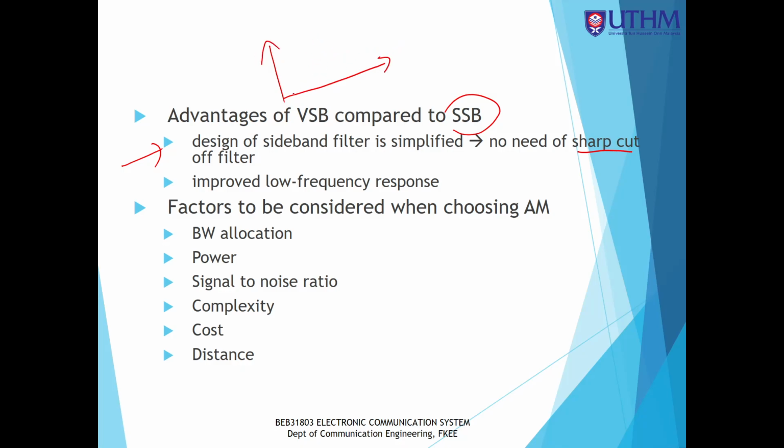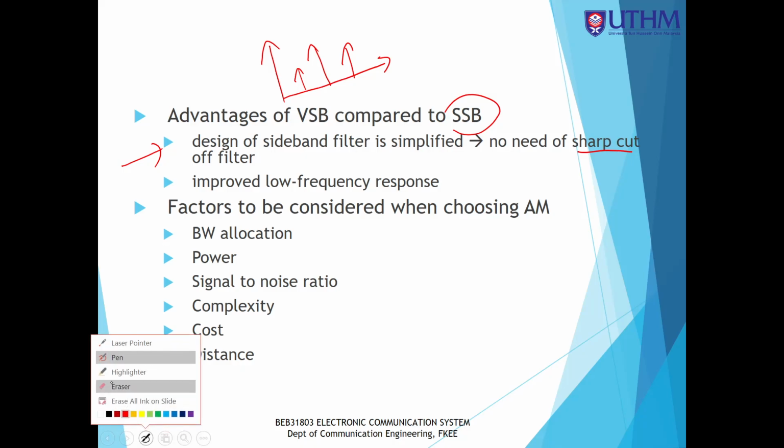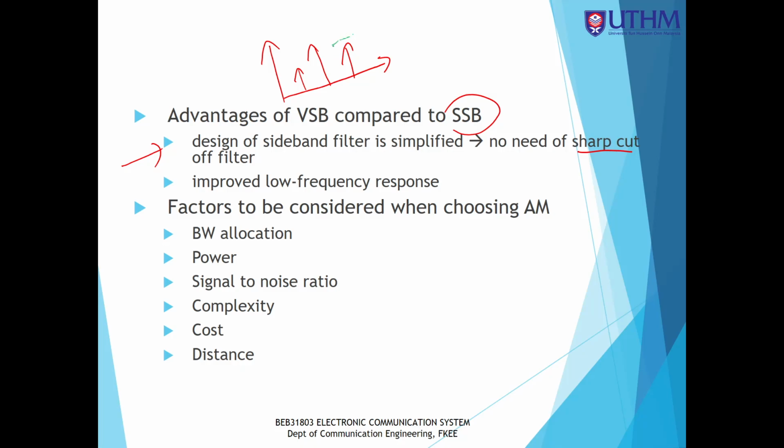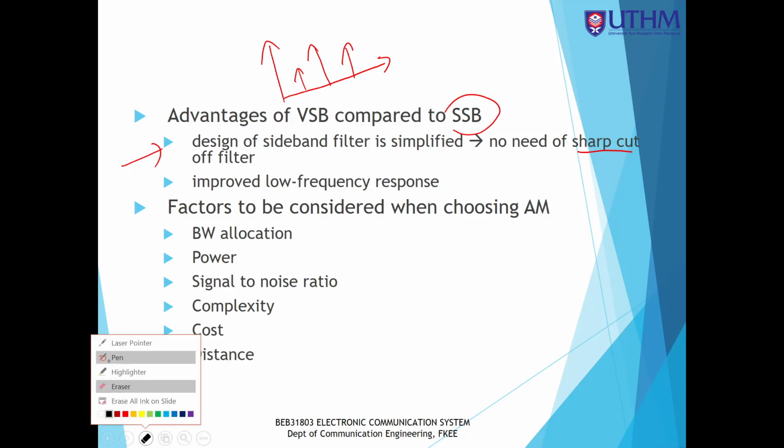Remember, for single sideband, for filtering design, ideally we want a filter that has a sharp cut-off, like this. This is the ideal case. That means we can take the upper sideband. However, in the real world scenario, the cut-off is not like that.